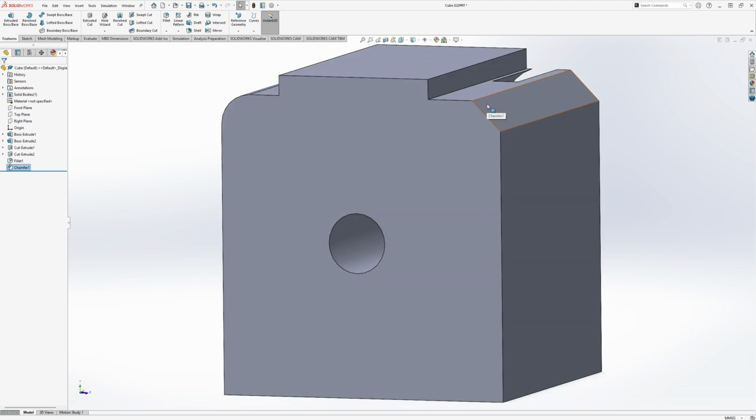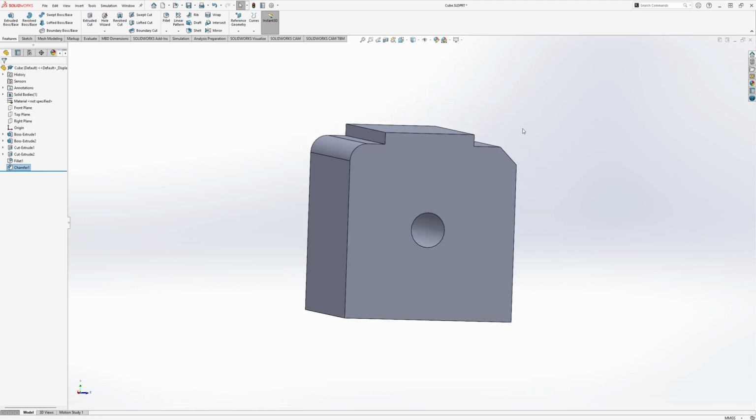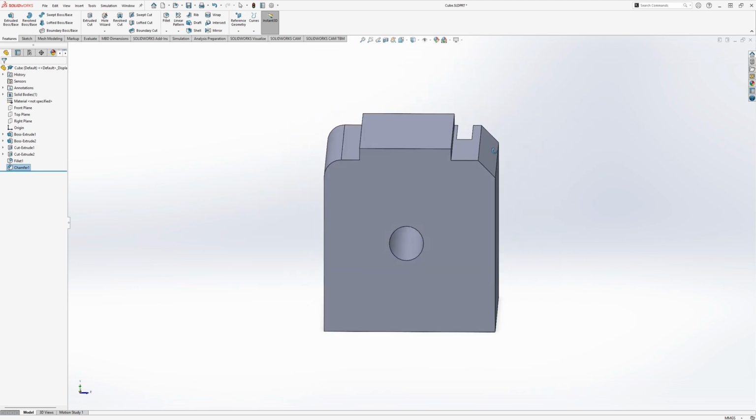This is a very heavy one. I would go for like 2 millimeters on a product like this if I was 3D printing it, or even machining this. But some people like to have fillets rather than chamfers. So that's that tool. For the other functions, we will have to go onto a new project. So let's save this file.